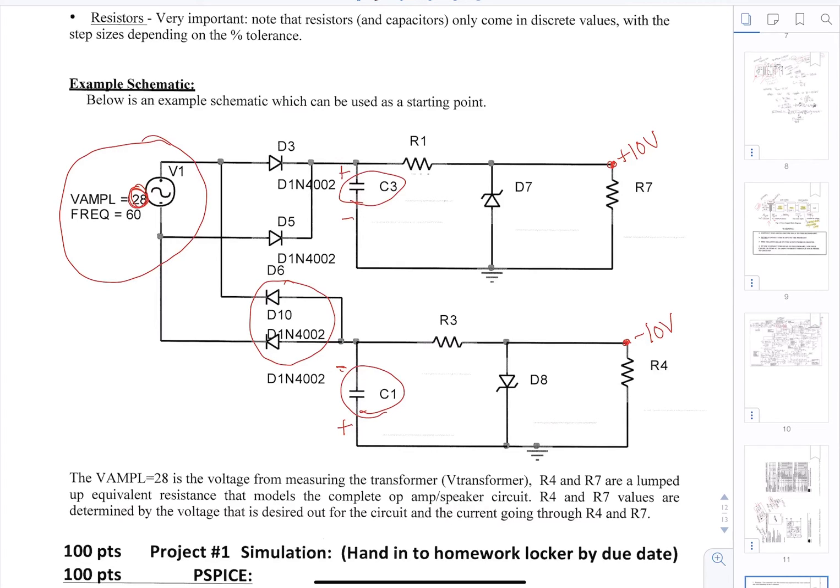And then here you're going to design that R1 and R3, similar to how I went through the example above. And then you want to choose the right Zener based on if you want 10 volts, 15 volts, 12 volts, sorry, that was negative, etc. You get to choose as the designer what value you actually want, and that's going to be determined by which Zener you're choosing.